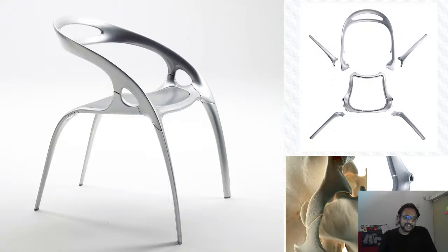Tejas is asking, why is it called die casting? It's not because somebody dies. It's because there is the mold. Everything that has a permanent mold is called a die. It's not called a mold. A mold is typically something which is not permanent; you would change it, or it gets modified somehow after the process is done. A die is something which is permanent, D-I-E. So that's why it's called die casting.